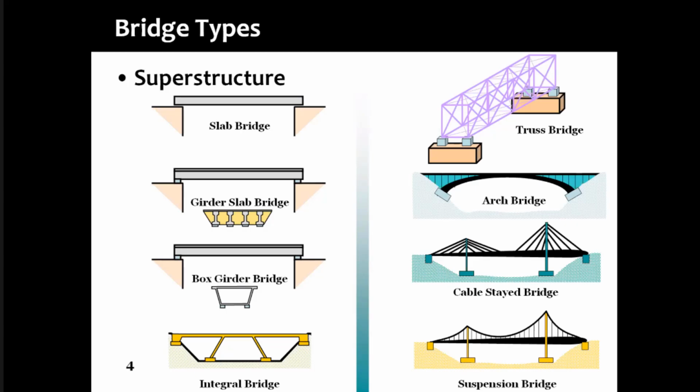So if you are a bridge designer, you will go and inspect the site when the vertical members are being built, definitely. And when the horizontal members are being built, you will notice that it is so critical that you will be there at site. In a building, in most cases, we are not visiting the site when the vertical members are being built, and we are visiting only when the horizontal are being built. And so we are putting the vertical members in jeopardy by not doing good quality supervision.